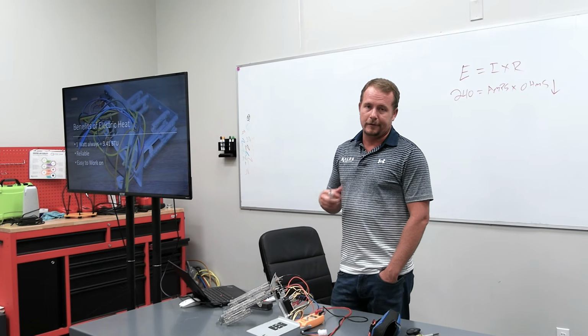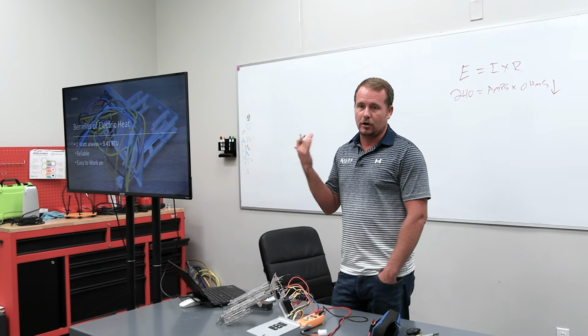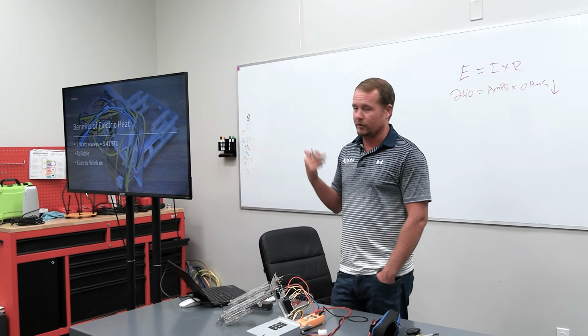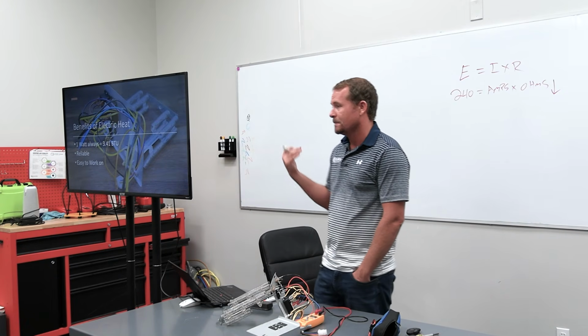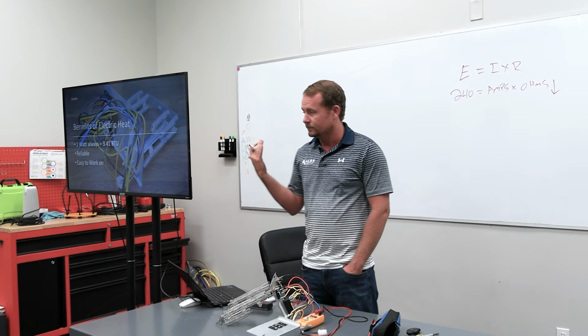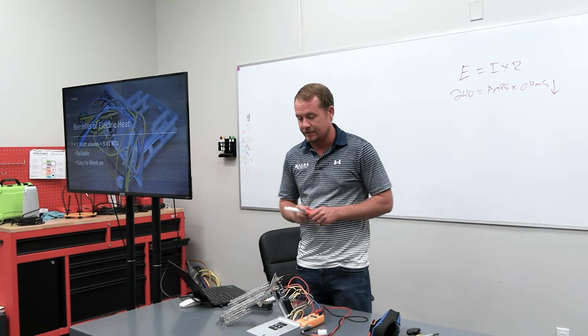Sometimes it's something like a piece of ductboard or a piece of cardboard. The cardboard will catch on fire, the ductboard won't do much other than block airflow. But sometimes it could be metallic, and that can lead to heat strip failure. Make sense? So make sure that you don't do that.